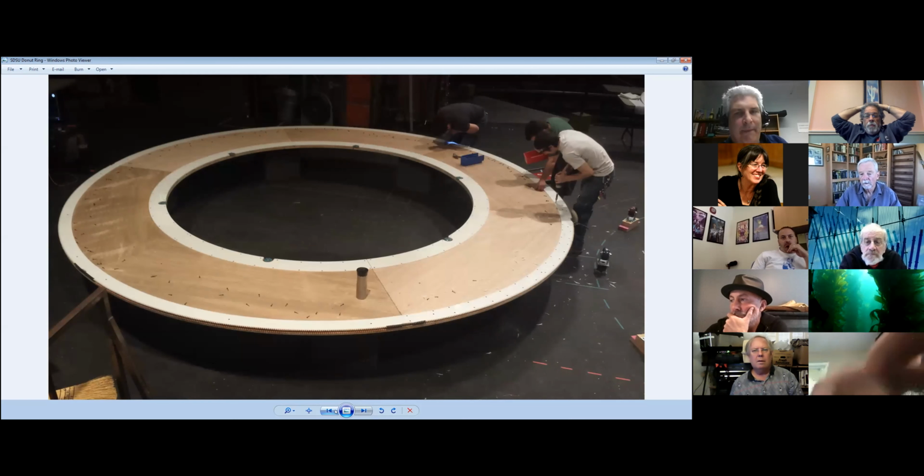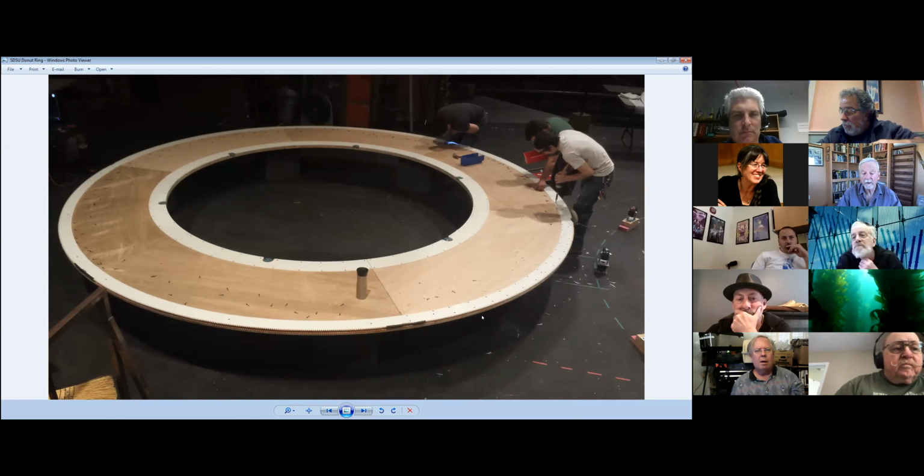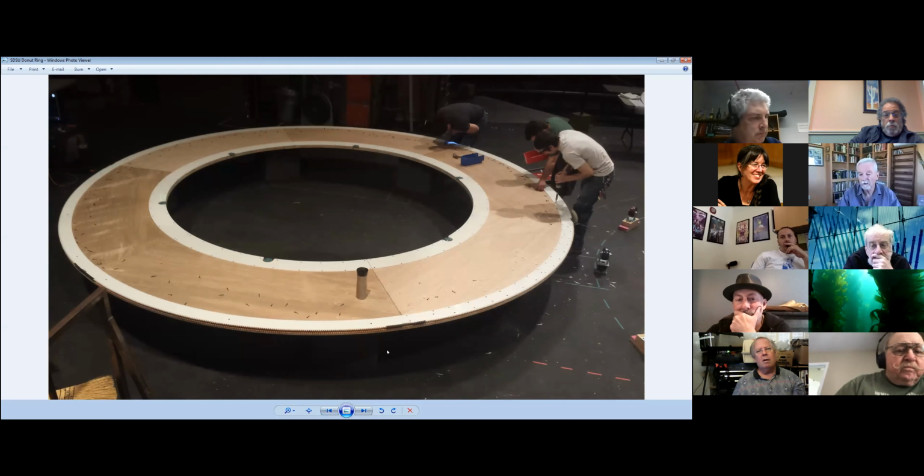One caveat I might add: you see down in this image, when we were putting the sprocket segments on, we put these little pieces of roller chain in there to get them properly distanced. Turns out that's a totally bogus idea. You have to wrap the whole thing with the chain. Otherwise, at some point it's going to be off just enough to make the train drop. So if you ever do it this way, make sure you wrap the whole thing with chain before you screw them down. We learned that one the hard way.